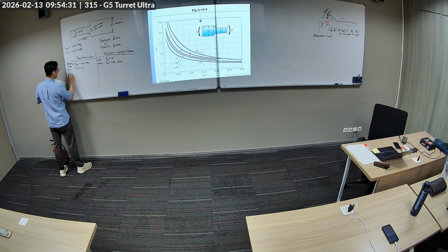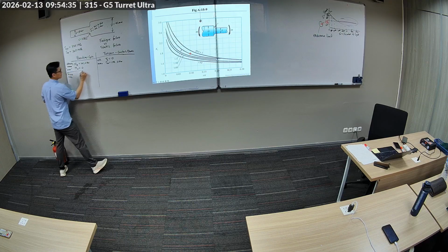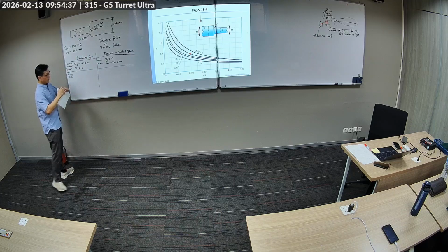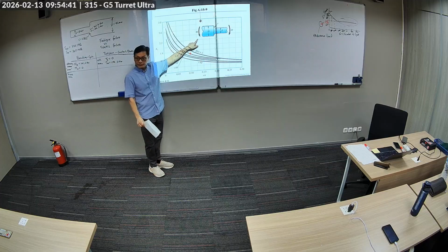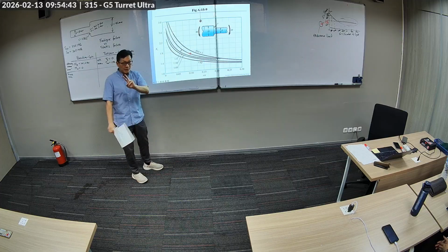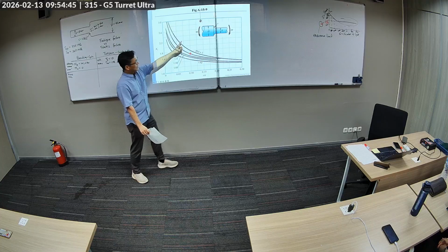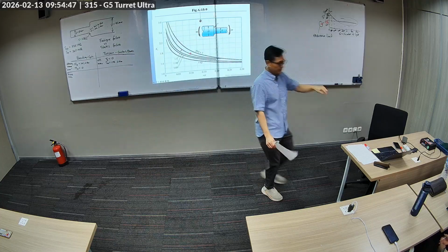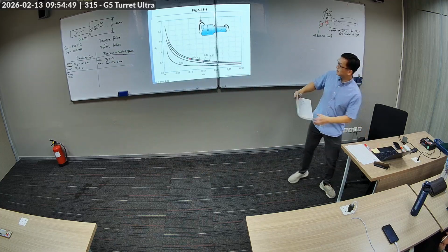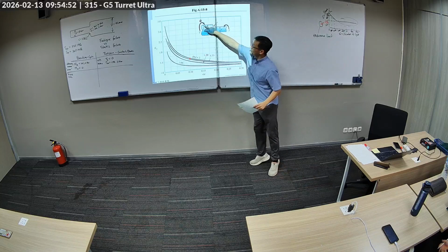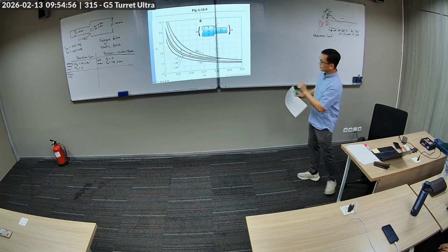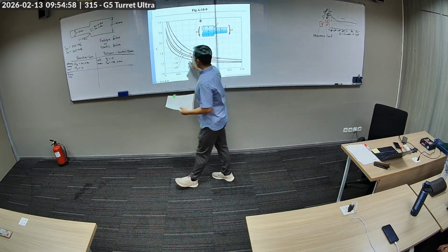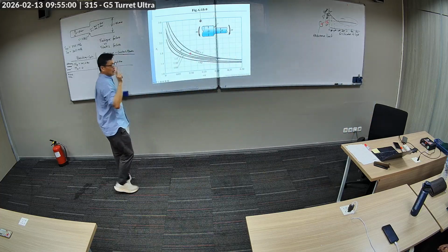Now let's talk about the stress concentration. Here is a chart for the bending moment. There are two kinds of chart. They look similar. Be careful. Look at this. This is M and this is T, torsion. Okay? Be careful. I will always give you two charts. So now in order to use this chart, I need two numbers.